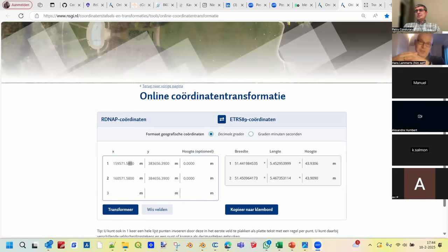It's a different method for IFC georeferencing. You have IFC 2x3, which has another way of georeferencing than IFC 4. The new IFC 4 format is what I showed you, and the IFC 2x3 method is with IfcSite, and it is based upon lat long, degrees. It's supported by IFC. It's in the IFC schema, but it's an older version versus a newer method.